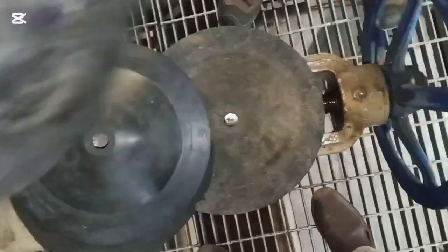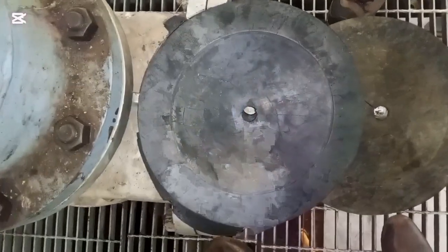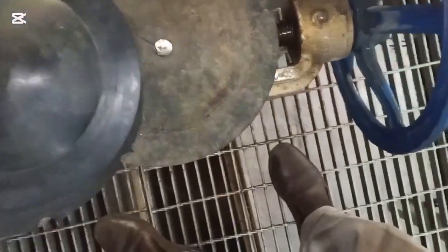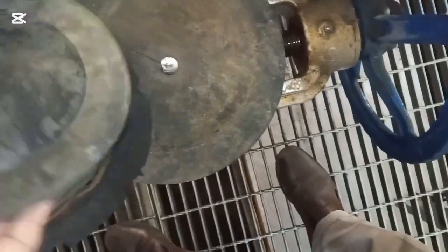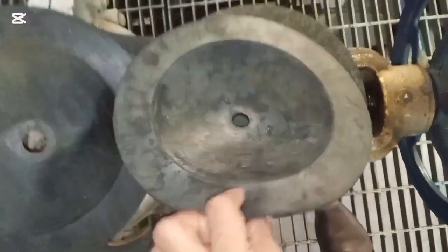The operating principle of the ejector is that the pressure energy in the motive fluid is converted to velocity energy by an adiabatic expansion in the converging or diverging nozzle. Due to the pressure drop of the motive fluid, it will create a low pressure zone before the mixing chamber.